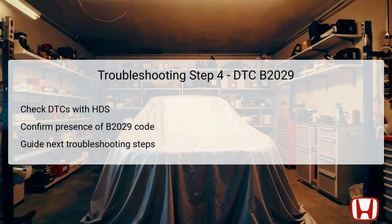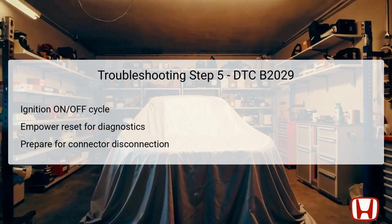Understanding the distinction between persistent and intermittent codes is crucial, as it guides technicians on what to focus their efforts on in subsequent diagnostics. This reiteration of checking DTCs not only confirms findings, but also validates the steps taken thus far. In this troubleshooting step, the technician should turn the ignition switch to the lock position, or utilize the engine start-stop button to select the off mode once again.